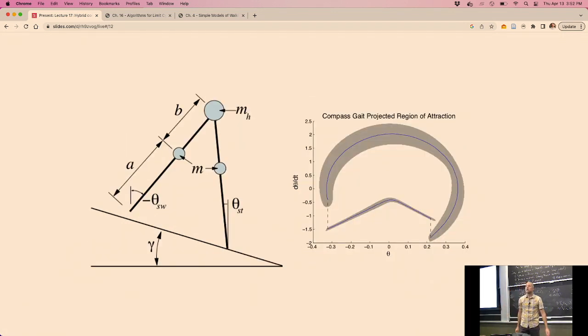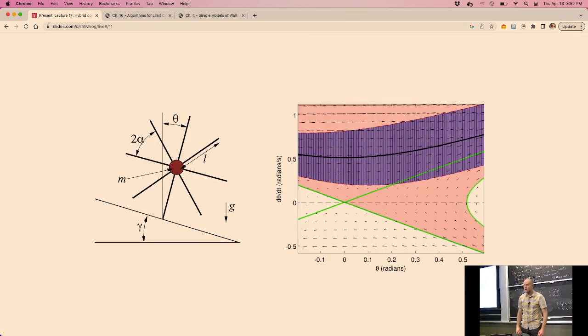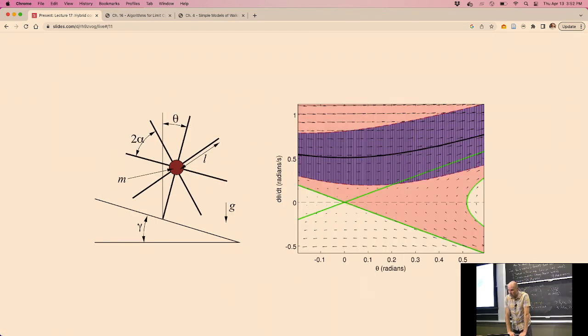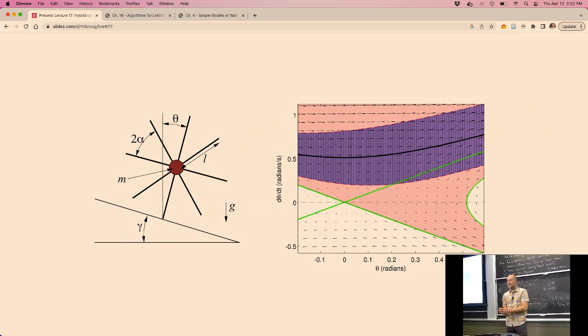Yeah? What if you don't really know what trajectory you want? Yep. So the Lyapunov-based tools out of the box want to know where zero is. There's a related set of tools based on contraction analysis, contraction theory, that just ask that trajectories locally are converging, and if that property holds over some interval, then you don't actually have to know where the zero is. They're slightly harder to work with numerically, but people have had a lot of success with these contraction metrics, control contraction metrics. I have some citations in the notes for it.